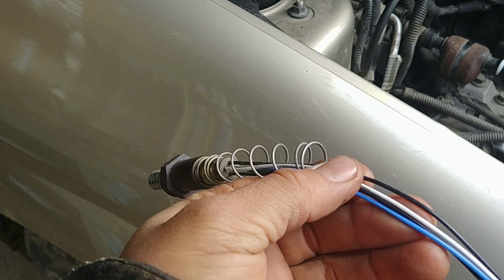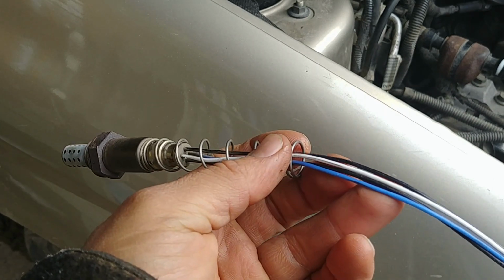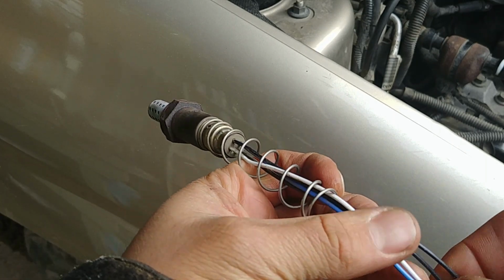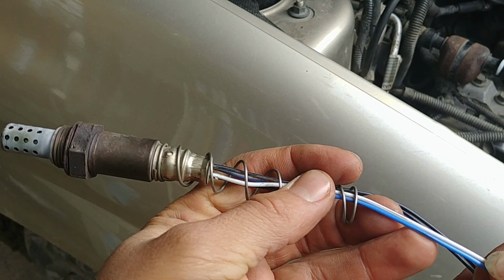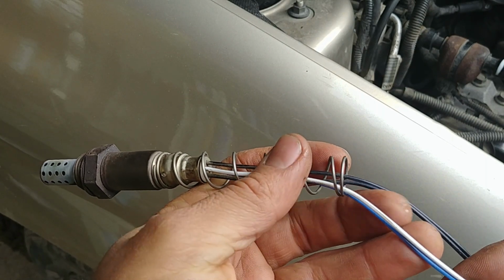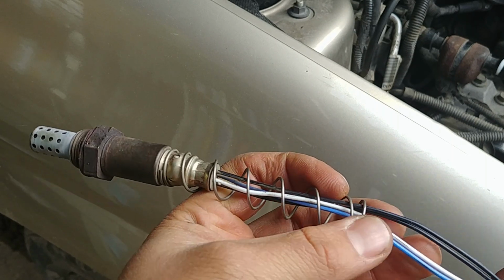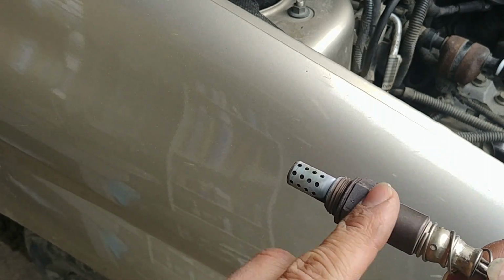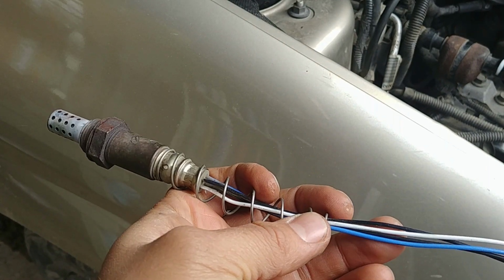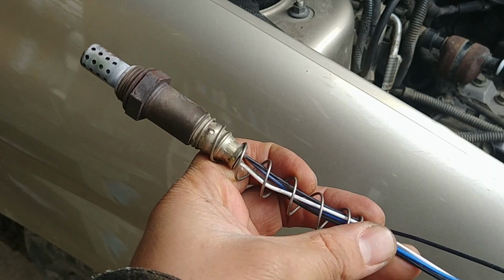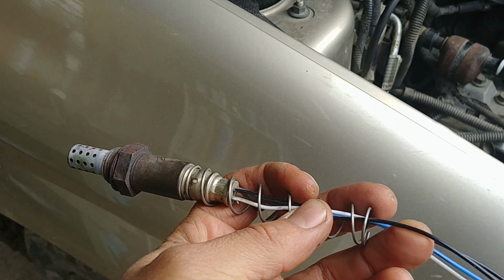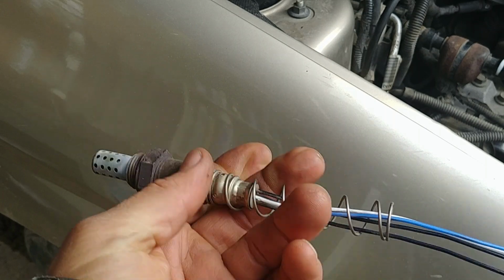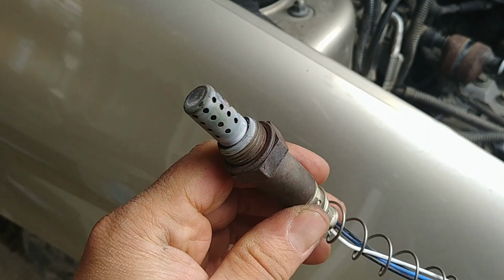Oxygen sensors could be 4 different types. Like this one, for example, has 4 wires. The 2 black wires are the heater element wires, plus a ground wire and a signal wire. But if your sensor has 1 wire, it means it's only a signal wire and the sensor is grounded to the chassis through the body. 2 wires mean it's more reliable. It has its own ground and signal wire. If you have 3 wires, it means only 1 wire is the heater wire circuit, which is better than nothing.